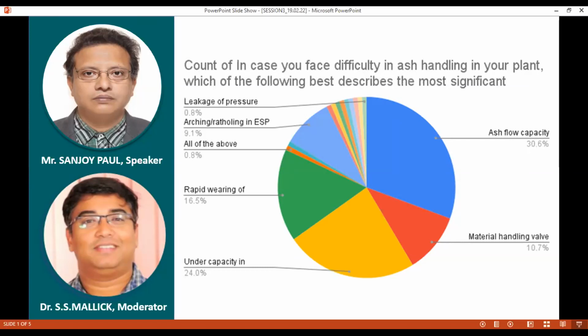So the next time when the valve tries to sit in the seal, the seating is not proper. The edge of the valve disc is not properly sitting into the seal, and what happens? The erosion starts from the edge.